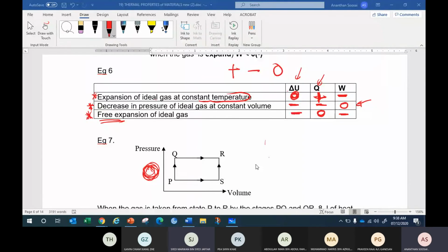Okay, so I never expect all of you to get this the first round. All the classes are like that. But if you manage to get the third line, good. So this is how the first law of thermodynamics is used. It is normally used to find the third quantity after you know the other two. The other two you need to find individually. Most of the time, work you can find individually. Another one you can find individually is sometimes changes of U, sometimes Q.